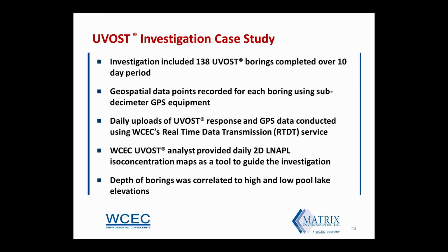And then we were doing daily uploads of all this data, including the UVOST and GPS data, using our real-time data transmission service. This allowed us to have our LIF UVOST analysts provide daily updates with a 2D LNAPL isolate concentration map. We use those maps in the field to guide the investigation to make sure that we are delineating this plume in all directions, horizontally and vertically.